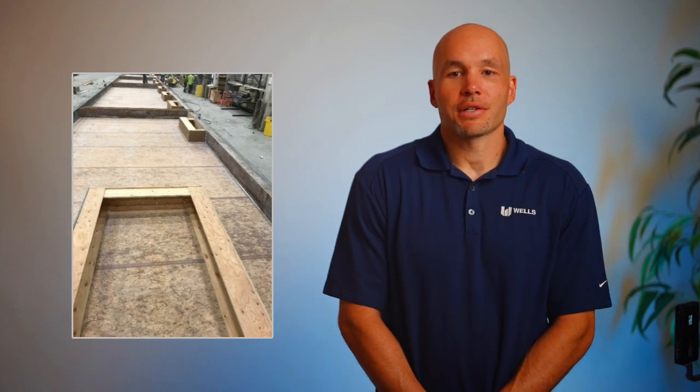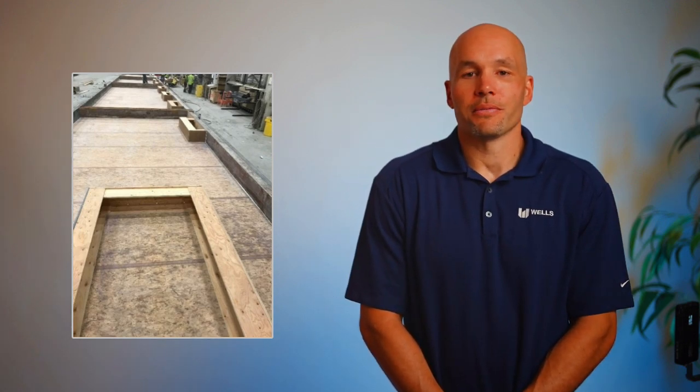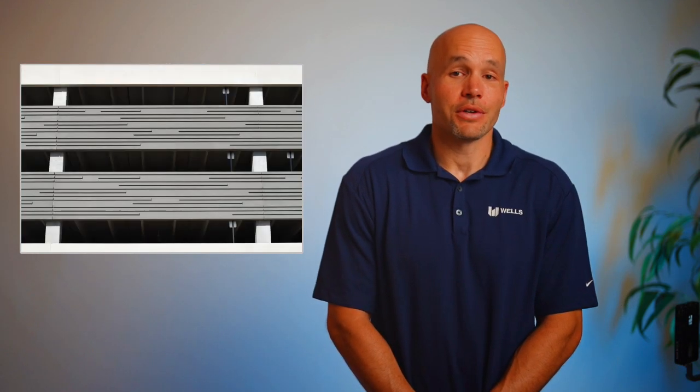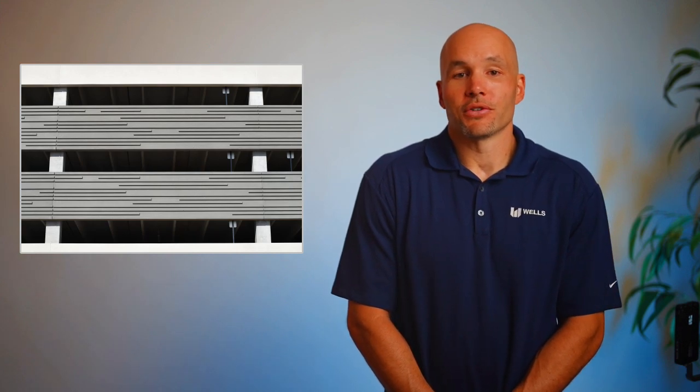There are a multitude of form configurations that can be used to produce wall panels. Standard sections can be cast on forms that are anywhere from 50 to 300 feet in length. Lifting devices are cast into the wall panel so that they can be safely lifted until the panel is safely placed in the structure. Custom forms can be utilized to produce custom shapes and add dramatic features to the walls. Some of these features include form liners and custom patterns that add texture to the finish of the panel. Thin brick is another material that can be used in precast wall panels to simulate a brick finish.